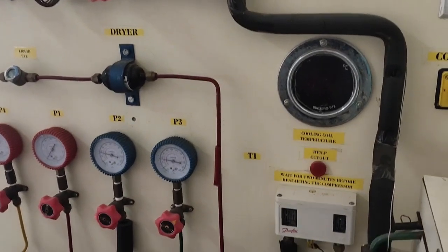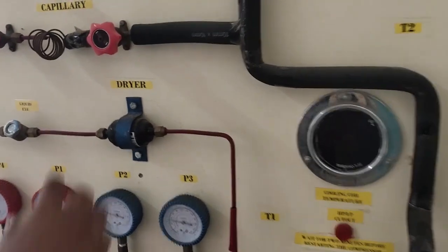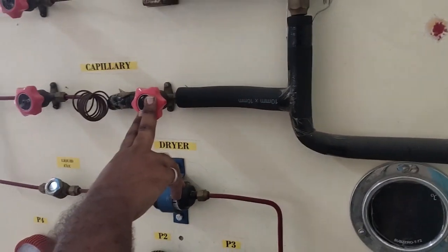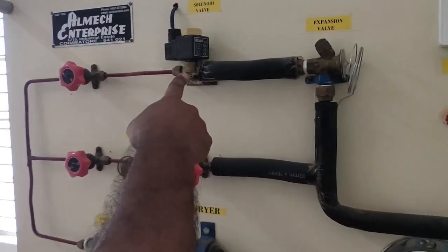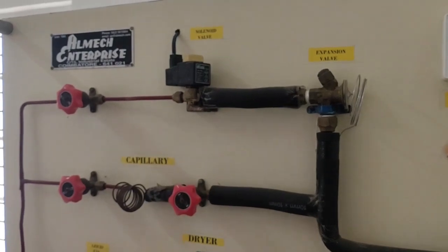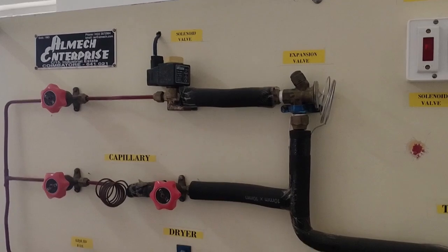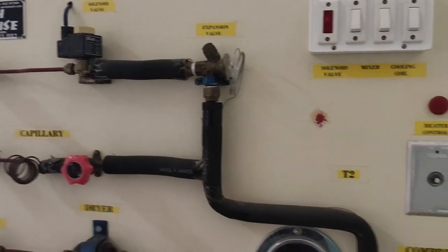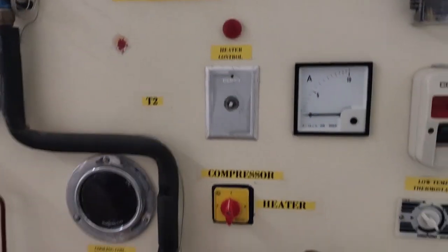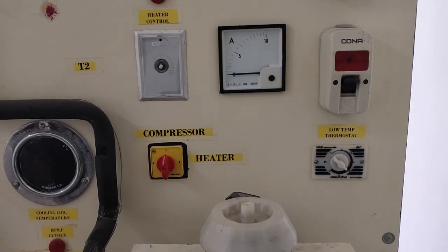So select the thermostatic expansion valve line by opening the shut-off valve in this line and closing one of the capillary lines. Either you can use the capillary tube for conducting this experiment, or you can use the solenoid valve. You have to choose any one of these. Then you have to start the compressor and run it for some time so that the chilled water temperature is lower than the given test temperature.